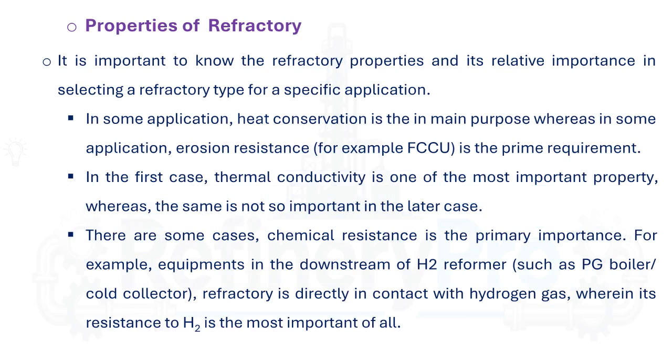Understanding refractory properties and their relative importance is absolutely fundamental to selecting the right material for your specific application. Here is a critical concept: not all properties are equally important in every situation. Let me give you some real-world examples. First scenario: in a furnace where your primary goal is heat conservation, thermal conductivity becomes your most critical property. You want a material that insulates effectively.